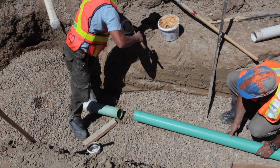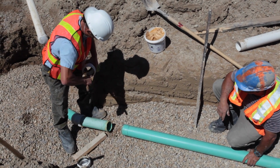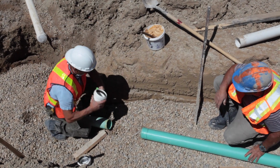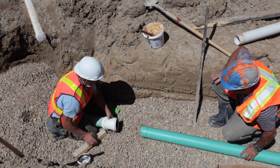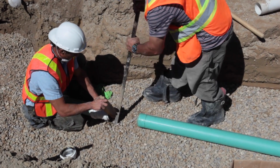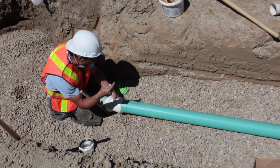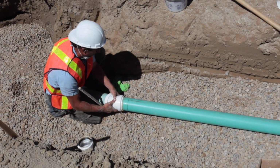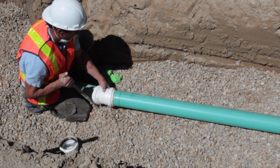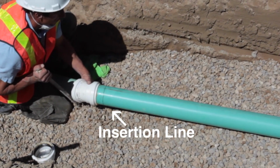Always keep a block of wood between the face of the pipe bell when pushing pieces together. This protects the pipe as well as ensures even distribution of the force pushing the pipe into the bell. Then, push the spigot into the bell until the insertion line of the spigot is even with the lip of the bell. For proper assembly, it is essential that we line up the pipe to ensure the spigot and the bell are aligned properly, always making sure not to insert the spigot into the bell beyond the insertion line.